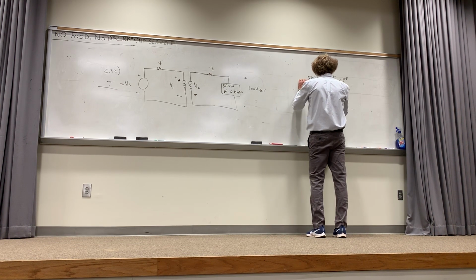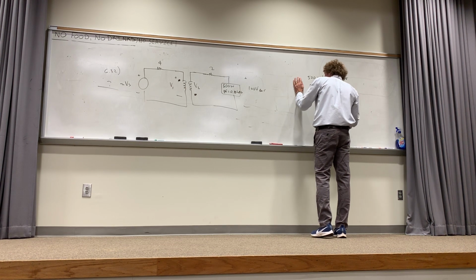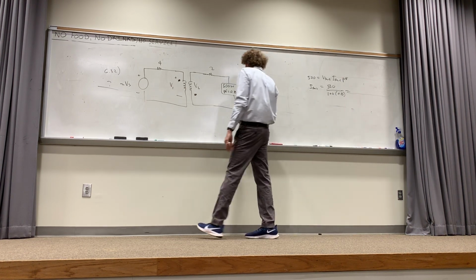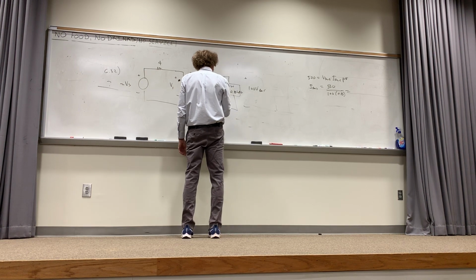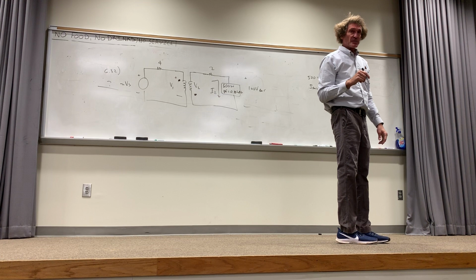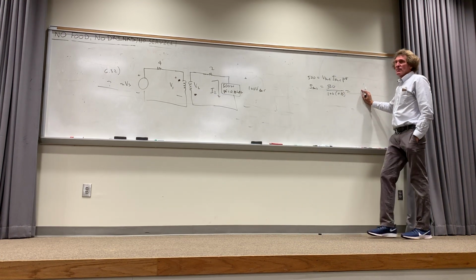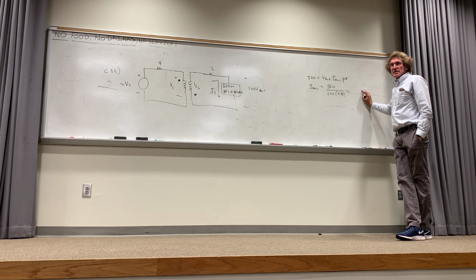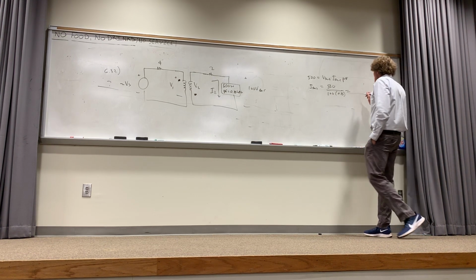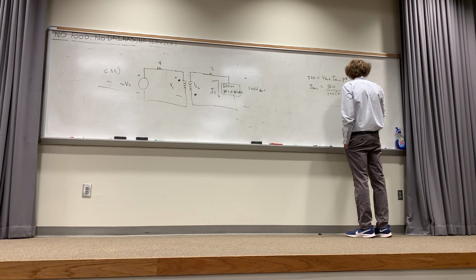I take 500 and I divide it by V, which is 100, and then I divide it by 0.8. And now I get the current, but the current I'm getting is this current. And it happens to be I2, if that dot's at the bottom. Do y'all see that, class? That's flowing into the dot. What is this value in magnitude, anyone? It's 5 over 0.8. Is that like 6, 7? 6.25. Yeah, 6.25. And that's really amps RMS, right?